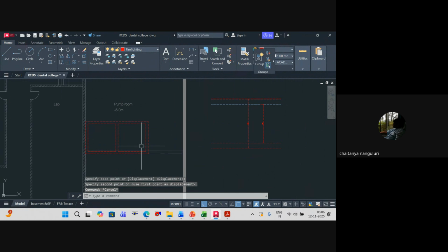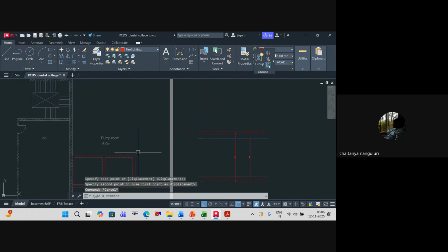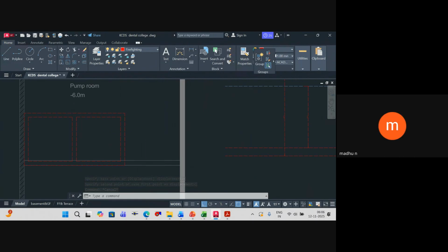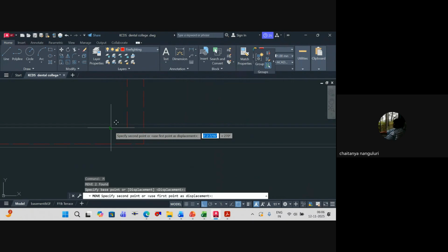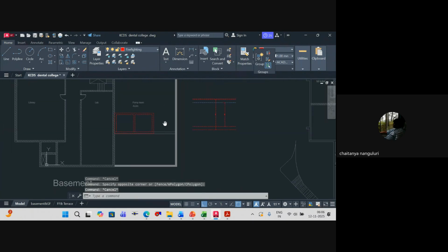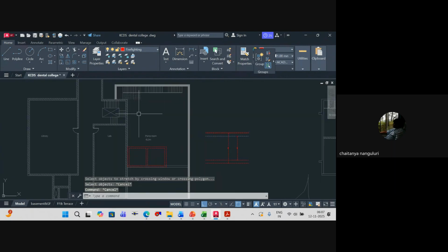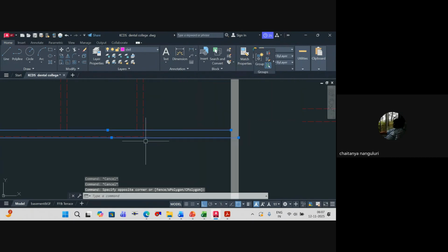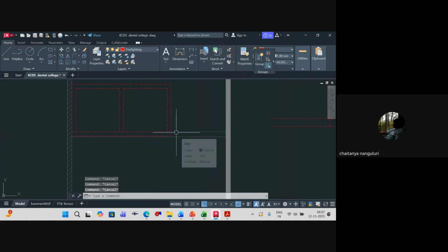Then according to your domestic demand, you can have a domestic tank as well. You agree? Okay, so this we can keep like this. So this is our fire tank. So in this entire area we can have our pumps and all. So your fire pumps and all, you can keep over here. Am I clear? And as per code, of course, many people wouldn't follow this, but technically, any other services, you shouldn't have inside your pump room, including plumbing. But you will see generally in a fire pump room, you will keep your plumbing pumps, your hydromatic system, everything will be there.